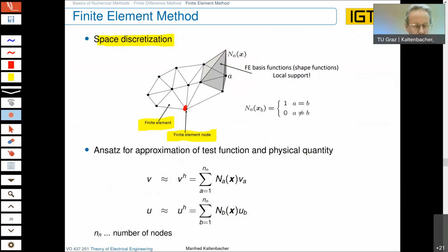Okay, now we discretize this domain in 2D quadrilaterals or triangles, in 3D all the bunches of geometric elements starting from tetrahedra up to hexahedral elements or pyramids, whatever you want. For all these elements, we have a machinery how we can approximate the physical quantity.